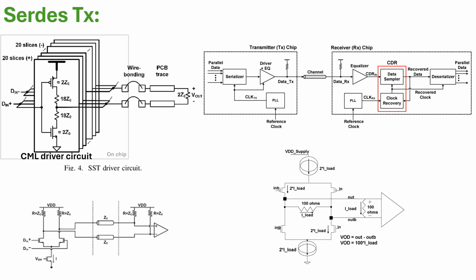The other one is CML logic, very similar to LVDS, which is also low voltage differential signaling. Termination really matters here also. These are the three architectures. We can list some more, but these are predominantly used in SerDes for the transmitting part of it.